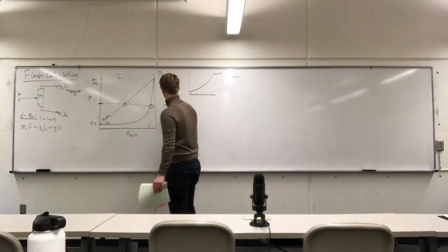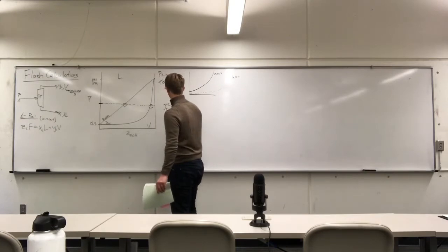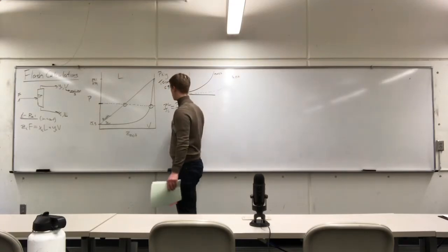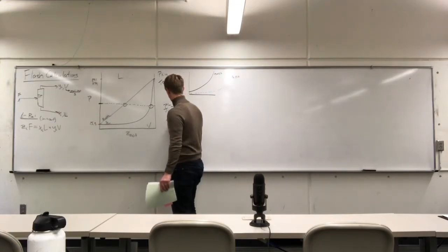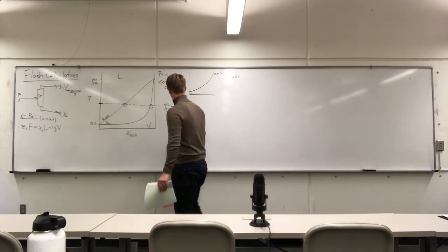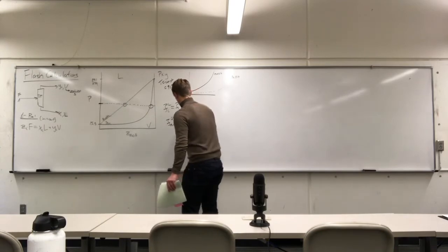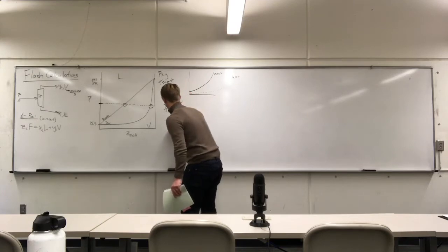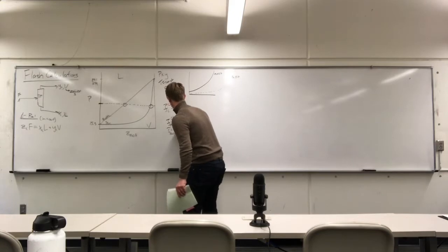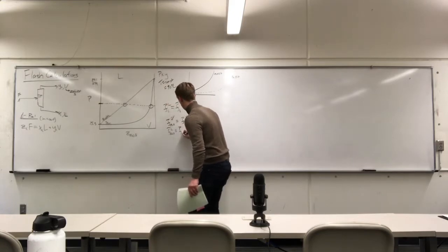Right? The partial fugacity of the liquid for species i is the partial fugacity for species i in the vapor phase. Now for this particular example here, this would be the partial fugacity of methanol liquid is equal to the partial fugacity of methanol vapor, and the second equation, partial fugacity of pentanol liquid is equal to the partial fugacity of pentanol vapor.